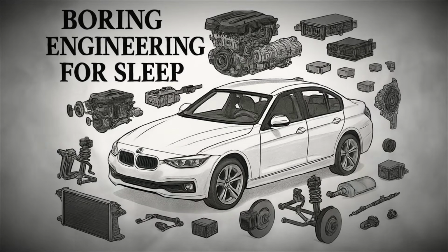Once the new gear is selected, releasing the pedal allows the pressure plate to press the disc back against the flywheel, re-establishing power transfer. The friction material on the clutch disc must provide enough grip to hold against the flywheel without slipping, while also being durable enough to withstand thousands of engagements over the life of the car. Because this material wears down with use, clutches are considered consumable components that eventually require replacement. The design of the clutch must balance smoothness with strength, since a sudden engagement would cause the car to jerk forward, while a weak grip would cause slippage and overheating.